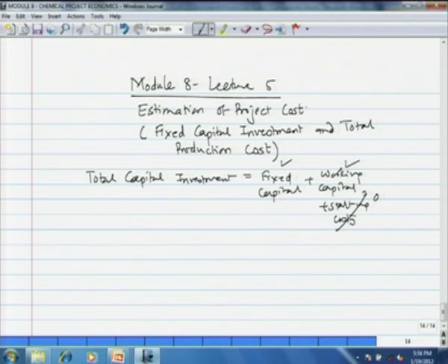A geographic boundary defining coverage of a specific project is called the battery limit, and usually this battery limit includes only the manufacturing area of the proposed plant in addition to other process equipment such as auxiliaries, but definitely not the storage, utilities, administrative buildings, so on and so forth, or the general auxiliaries like steam and cooling water. These are usually not included in battery limit.